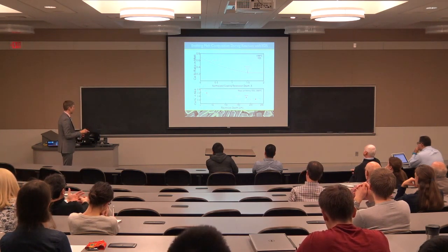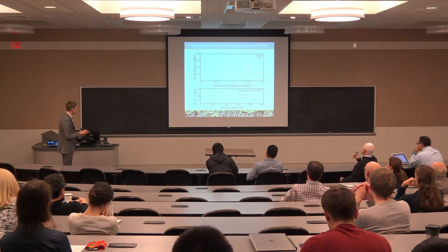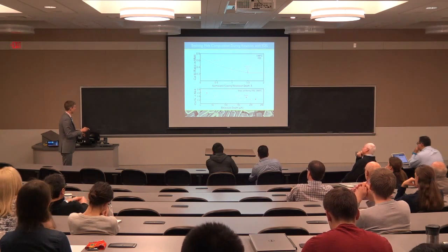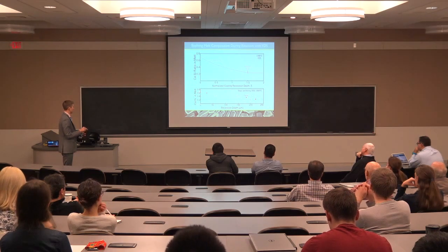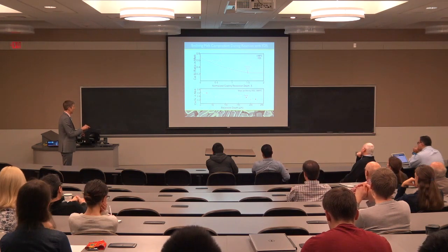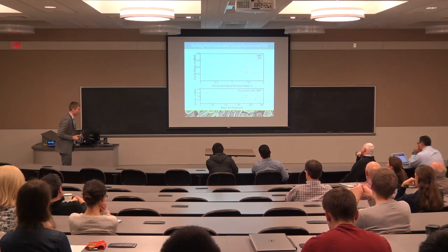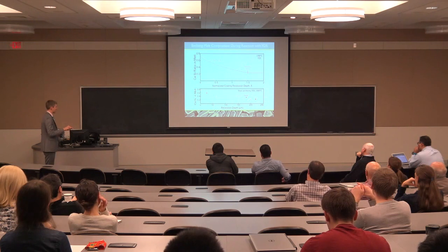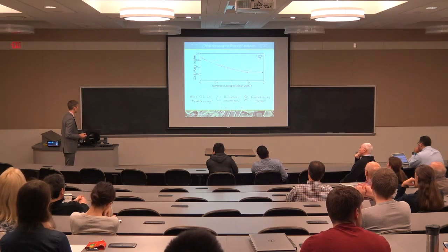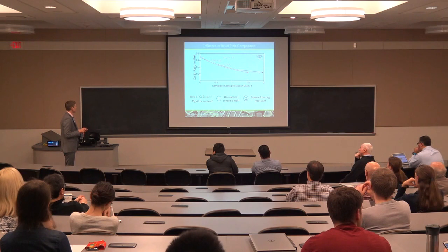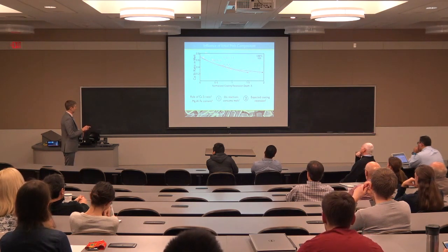Before we did that, in order to assess whether this is actually the right behavior, we compared our calculation results with data from actual coating recession experiments, where they measured the calcium-silicon ratio in the melt as a function of recession depth, and the results agree quite well. When we get down to this threshold indicated by this blue line, the reaction stops. As you go to longer and longer times, the melt just sits on the surface and no further reaction takes place. So we can then pick a range of different deposit compositions.